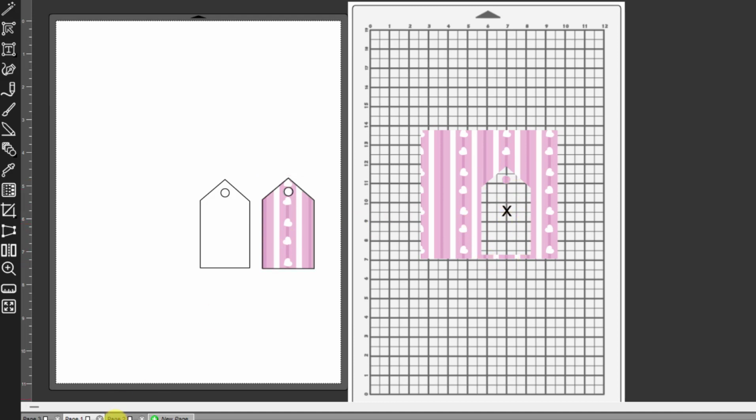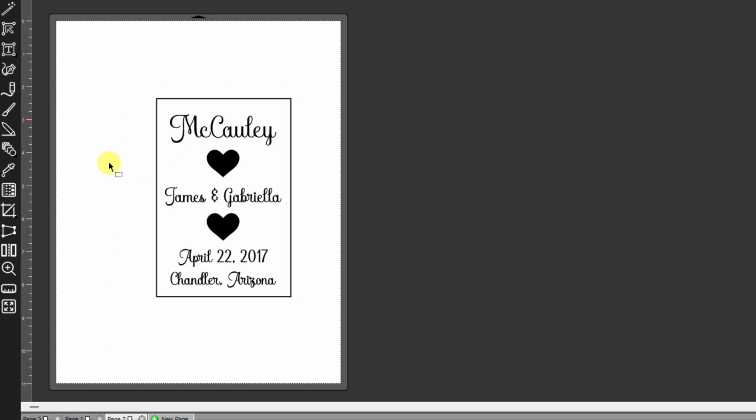The other one is engraving. With engraving, let's say you're going to engrave on a 4 by 6 inch piece of acrylic or a mirror or something like that, and you've measured it. And this one is kind of important for center point mode. You want to have some object in which you're going to be able to determine where the middle of the object is, for setting the origin. You can't have some kind of funky shape, because it's going to make it really hard to figure out where that center point is. So here I went ahead and set up a 4 by 6 rectangle,